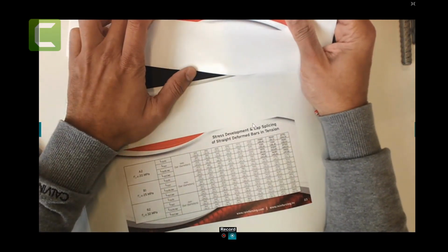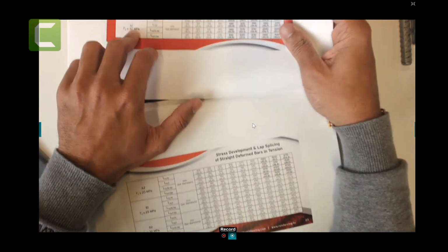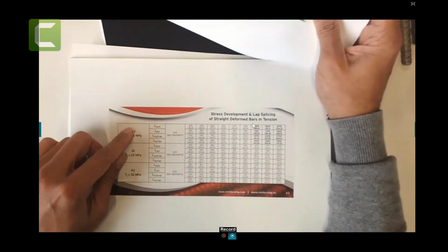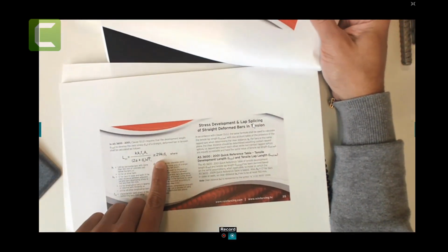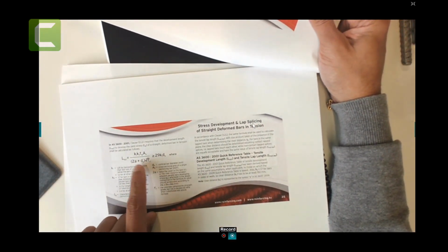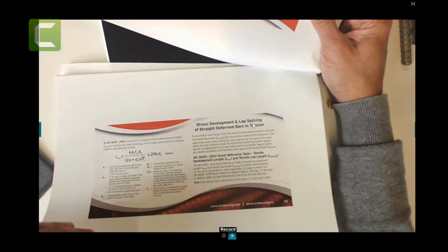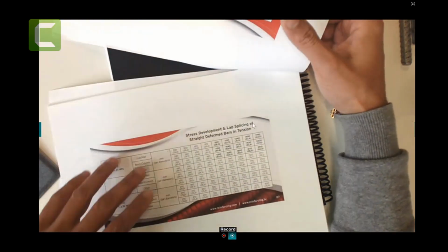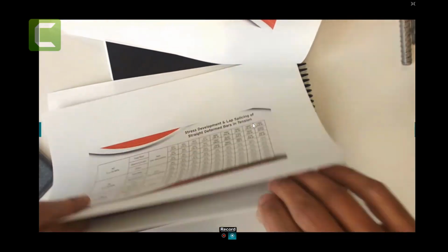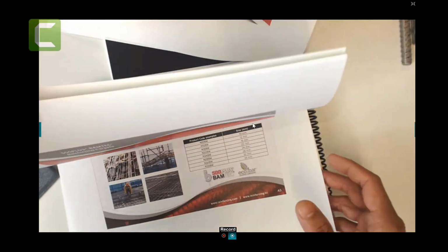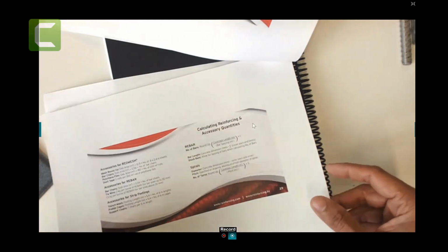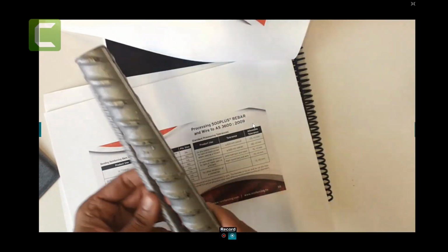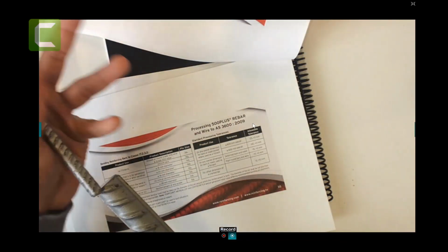There is a classification, A1 classification, you know, durability, A1 classification and A2 classification and B1 classification and so on. So they use this 29. You remember this minimum and K1, K2. I think we use the latest one, but yeah, they have this one. I think you remember there is a congestion. Probably they have these couplings. Couplings meaning that sometimes when you have a bar, it is too congested to have this lap splice. Sometimes they have a coupling.